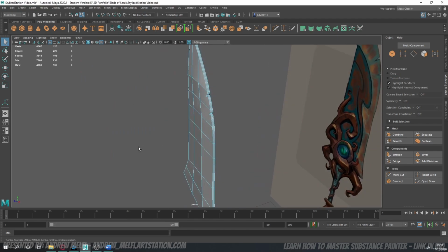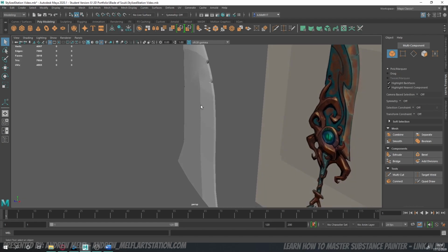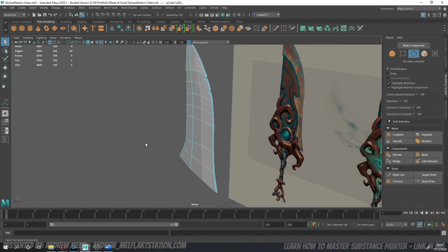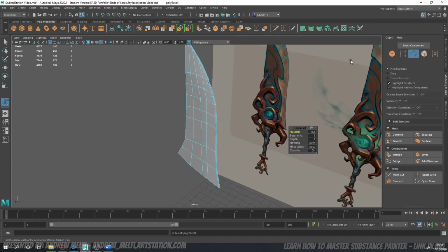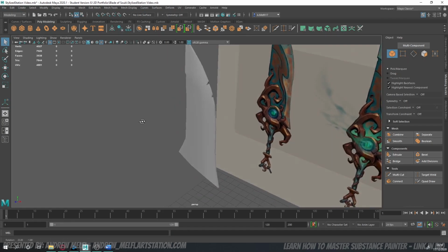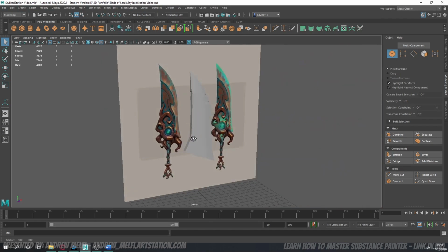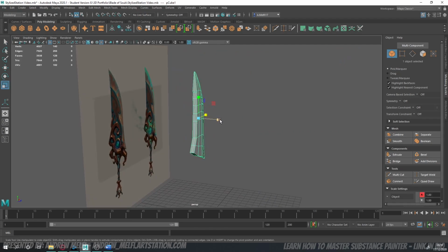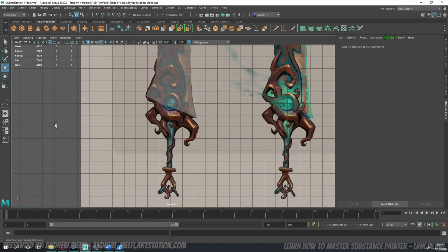So having done that, it's kind of made a slight crease in the object, as you can see down there. See that line? So what I'm going to do is select this, which selects it on the other side as well because they're connected. Bevel. And that'll make it smoother. So that'll smooth it out like that. So now I think the blade's pretty much done. A few little tweaks here and there, maybe make it a little bit thinner, but for the most part that bit's done.